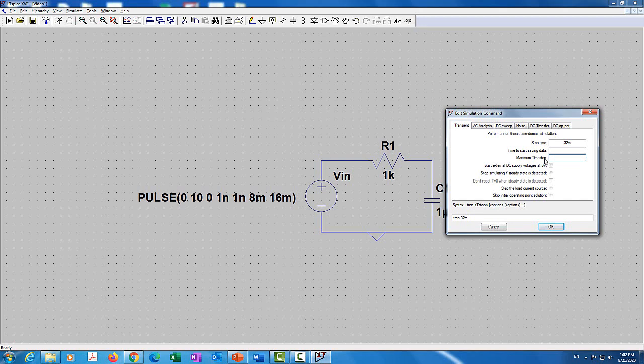So usually what you want to do is choose a good value to be around 1,000 samples per cycle. I know that each cycle here is around 16 milliseconds. So I would say like 10 micro sounds good. I can even go a little bit lower. I would say 1 micro, right?